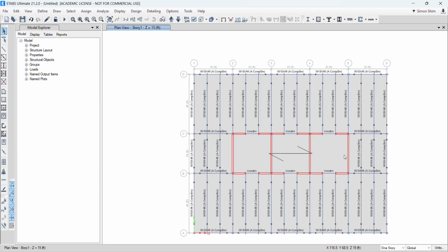Up to here, because this is a high-rise building, we are using concrete walls. We placed the concrete wall to align with our planning requirement, because this is an elevator hall, so you cannot put in a full wall. I just drew the wall, most likely an I-shaped type of layout, and I tie the walls together with the concrete beam.